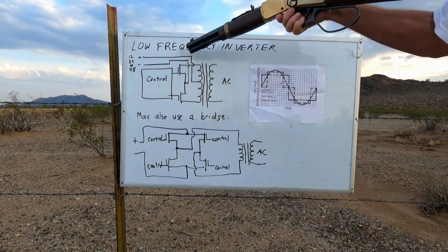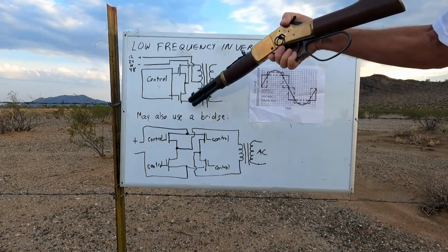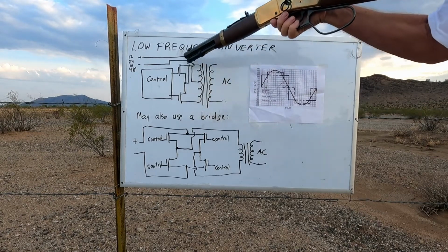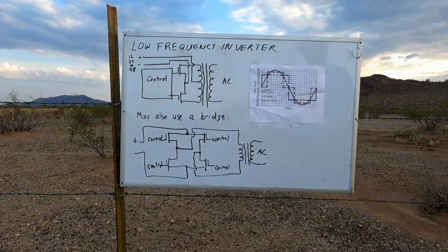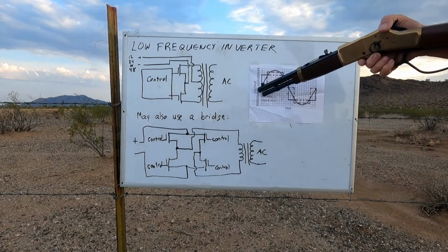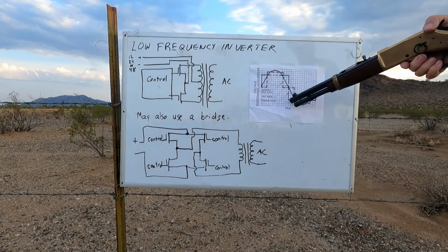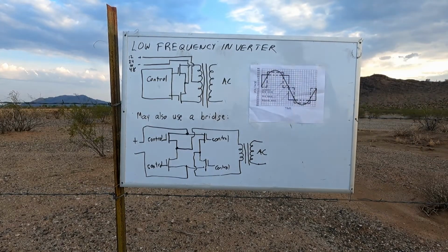It accepts your DC input. The transistors switch alternately on each half into a transformer that then steps up the AC output. And the very earliest inverters might have had what is called a square wave output, which simply went up and down and generated the AC output.